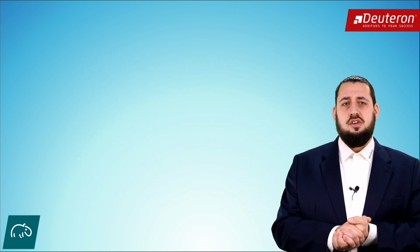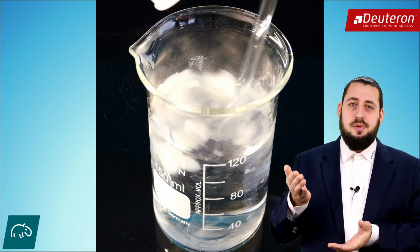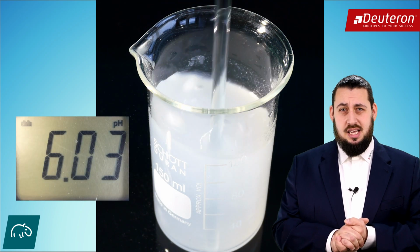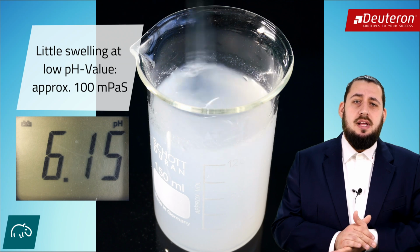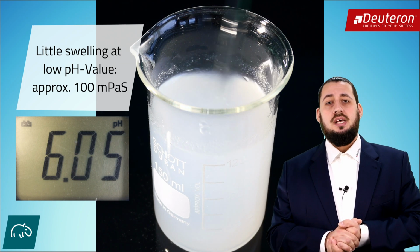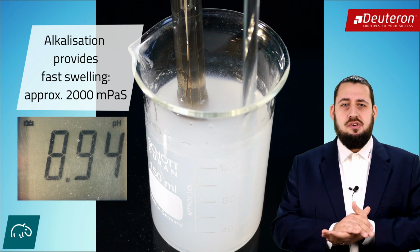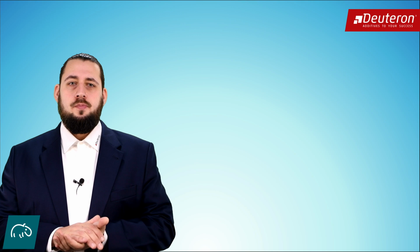For the incorporation of the glyoxal-coated grades, we have one more hint. The higher the pH value, the faster the swelling occurs. If the powders are stirred in at pH values below 7, they will be well distributed in the water. Then the pH value can be increased. Now the swelling occurs and the final viscosity will be achieved quickly.